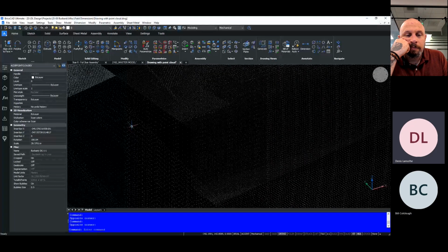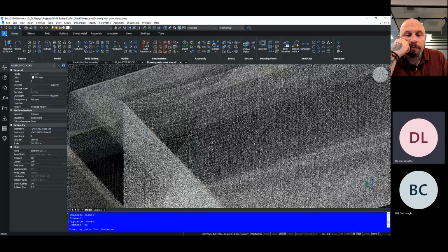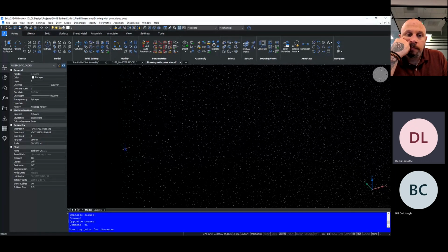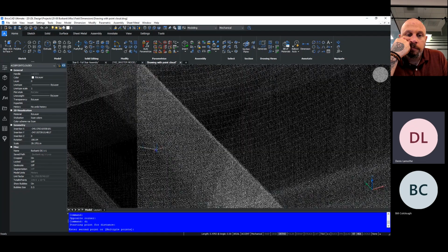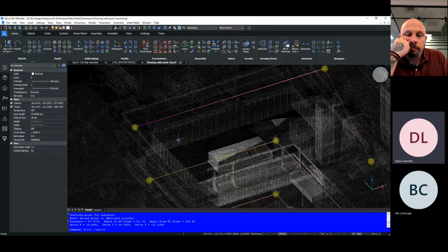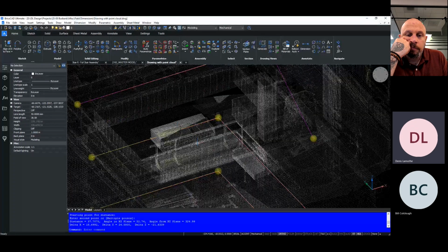We're fairly new at using point clouds. I expect we'll have to do a little additional training to develop a standard for how we measure from one point to another. But it's a means for us to get a fairly complete survey done fairly quickly.